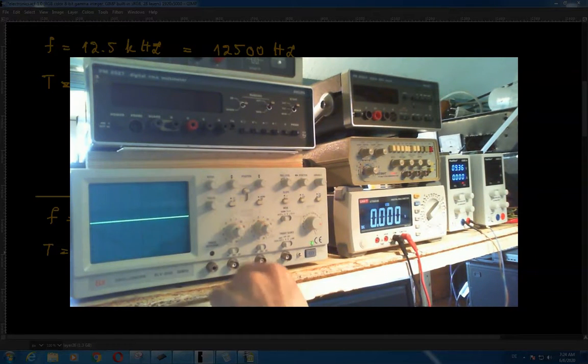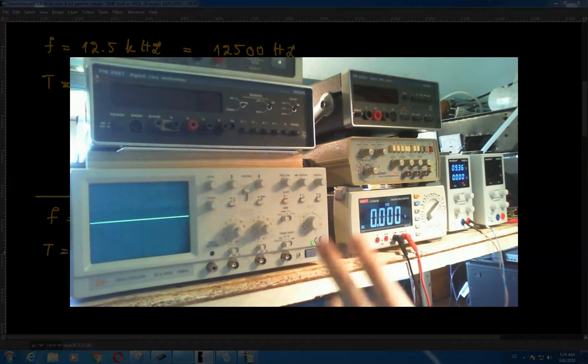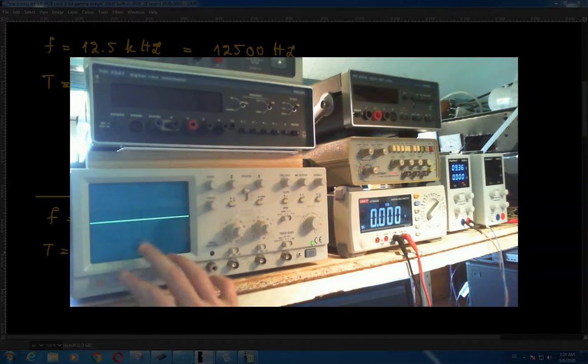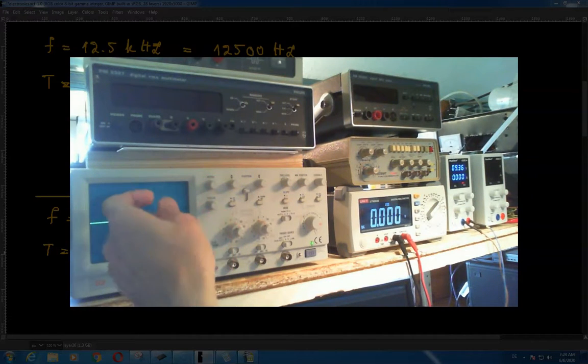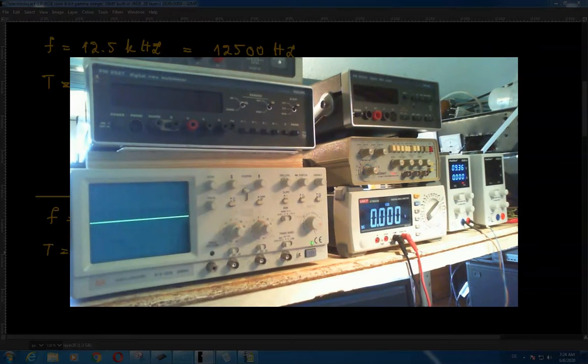So I connect this, and this oscilloscope has two channels, channel 1 and channel 2, and you can make measurements on both channels, kind of simultaneously, because you have only a single beam over here. This is a CRT screen, just like an old TV. There is a gun at the back of this CRT screen that is shooting a beam of electrons at this screen, right?